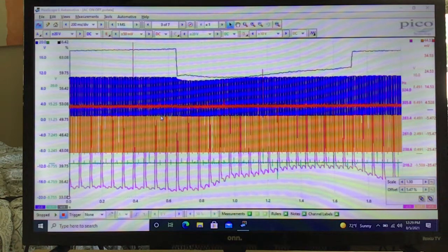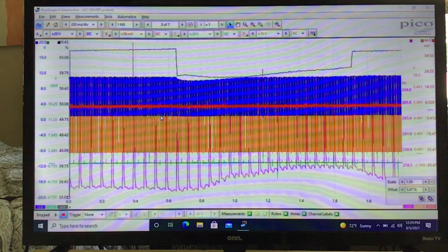You remember from the first 2 videos, we had 4 scope signals and 2 math channels. Our black math channel is the duty cycle, and our sort of magenta one is a math channel for RPM/frequency, taken from the crank signal, which is in orange. Our duty cycle signal is in blue. Basically, the gist of this section of the video, we're going to talk about just the AC on, AC off.